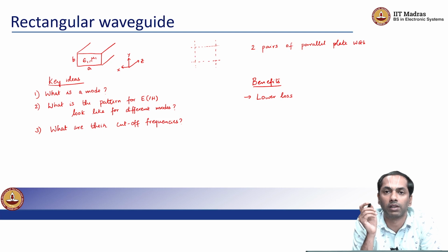So remember that with the TEM mode being confined in the transmission lines, the central conductor, right, as it's carrying currents at very high frequencies, we know about the skin effect that actually pushes these currents closer to the surface, right, of the conductor, and this normally leads to an increase in the resistance seen by the charge carriers, right.